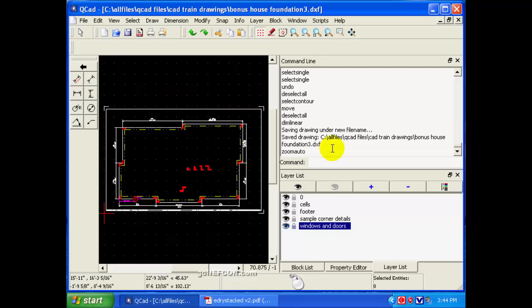In this lesson we're going to address the issues required to establish wall cells. A wall cell is a poured concrete cell in the blocks where there's a rebar reinforcing rod inside that poured cell.